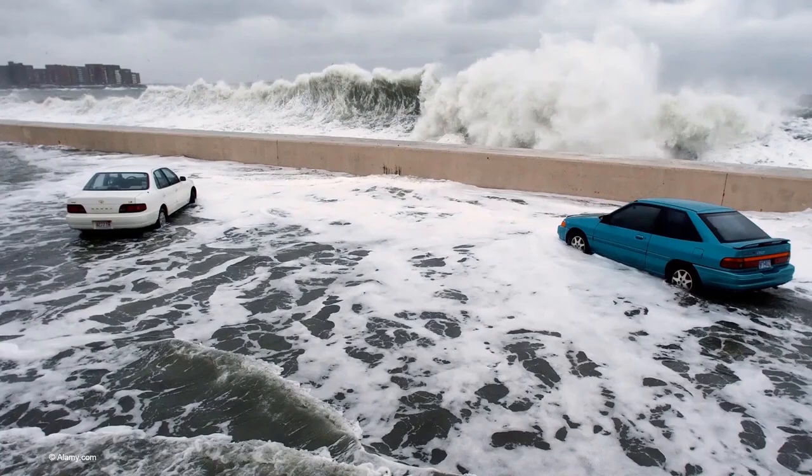So this is something that MIKE 21 Wave FM is capable of simulating, some of this coastal flooding. And of course, as we see in this picture, we can't resolve this spraying, but we can resolve the green water overtopping, which comprises most of the overtopping discharge in any given scenario. That is also the one that causes the most damage.